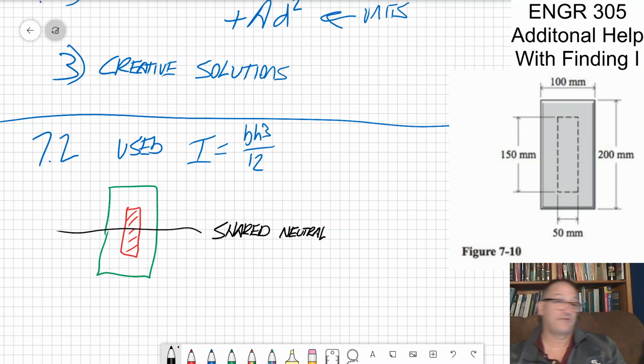honestly, that's the first thing we should be talking about, this neutral axis, because the first thing you've got to do is figure out where the centroid of area is. That's one of the things we didn't go through in the proofs that show up in sections 7.3 and 7.4: this neutral axis, the centroid of area, is where the bending takes place.